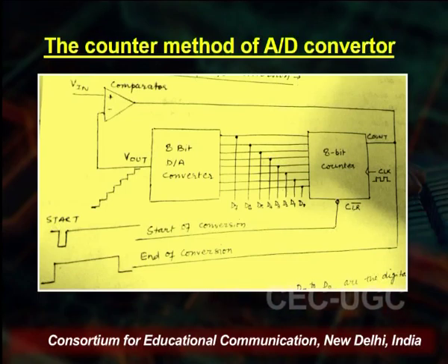In open loop configuration, the gain is very high, of the order of 200,000, that is 2 lakh. So, the op-amp would operate only at positive saturation and negative saturation. If the input analog voltage is very small, in the order of microvolts, then this circuit will not give a very stable response. The stability of the circuit depends upon the input that we are handling.